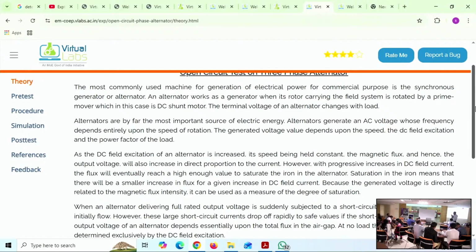We first give a lesser value of DC voltage to the armature coil, say 1 volt, with 1 ammeter and 1 voltmeter across the armature winding. We give 1 volt, 2 volt, 3 volt, maximum say 5, up to our number of readings, less than 10 volts, but not like 200 volts, 100 plus volts, or more than 50 volts.